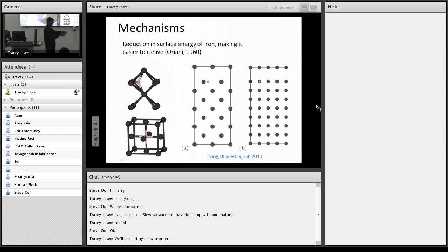So what you do is you take a number of atoms in your computer, you place a hydrogen atom inside that cluster, and then you have to cleave it. Now how do we cleave this? Well, the spacing between this layer and this layer is much larger than the spacing here, and you increase that vacuum space until it doesn't make much of a difference to the total energy of the system. That means you've created a cleavage of material, and then you work out whether hydrogen reduces the surface energy or not.